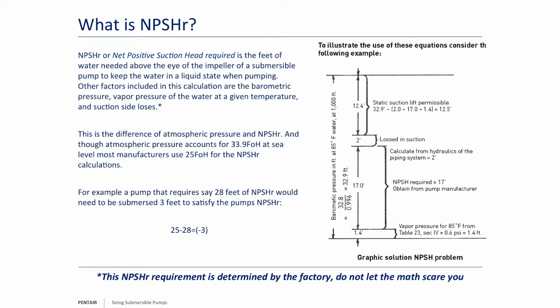First of all, if I have a pipe that's 35 feet long and I'm at sea level and I put a vacuum, a perfect vacuum, on top of that pipe, I would draw water up 33.9 feet. That's because I have 14.7 pounds of air pressure pushing down on the water at sea level. 14.7 times 2.31 is 33.9.